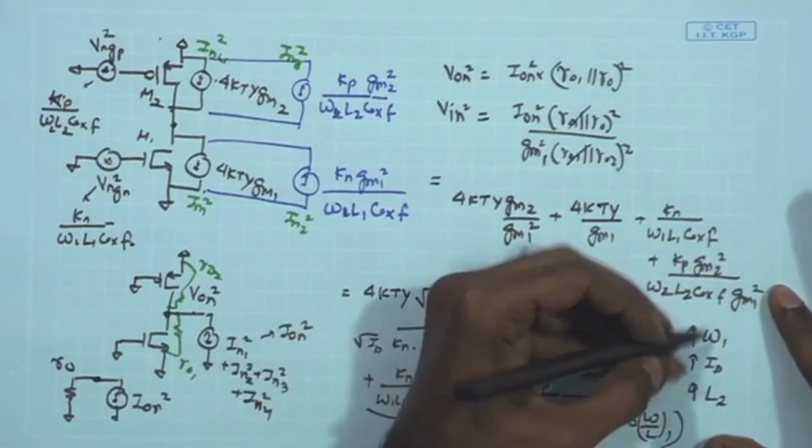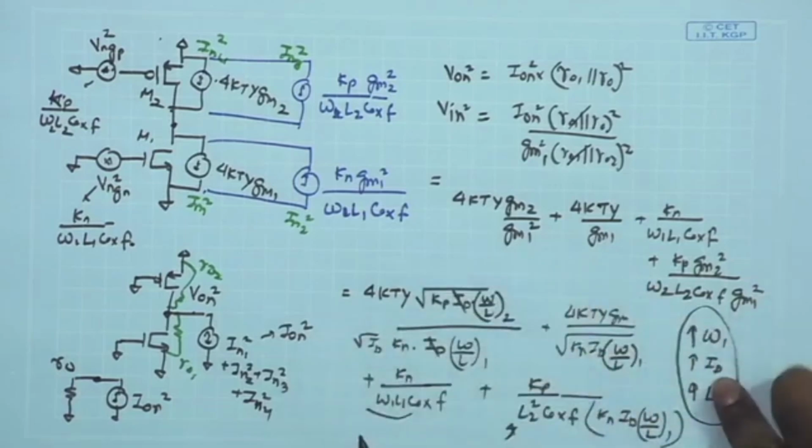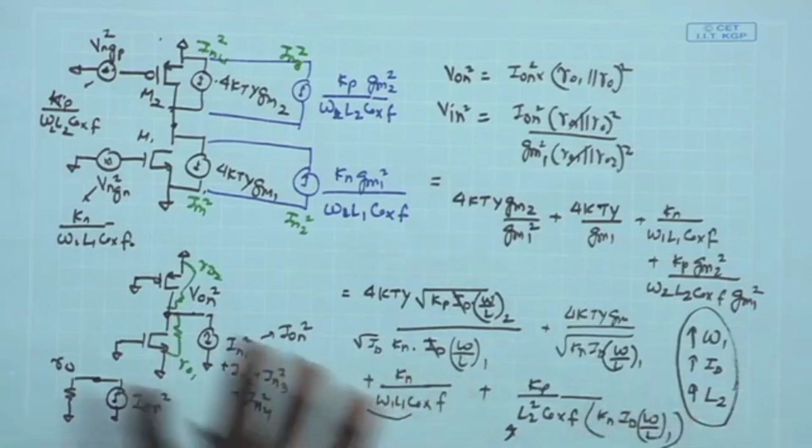So we have looked at the sizing considerations. From the point of view of sizing, you can minimize the thermal noise contribution and try to push the 1 upon f noise towards lower frequency. But if your signal content lies at even lower frequencies, then what are the steps to be taken? We need to address that.